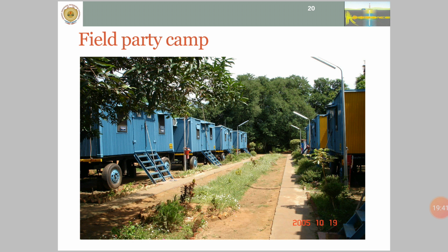It is important to check on the software whether the record which has been recorded gives a good signal to noise ratio, whether the target length is good, and whether the horizons of interest which we would like to map are well recorded or not. A decision is then taken whether to accept or reject it, and then re-record it next day.